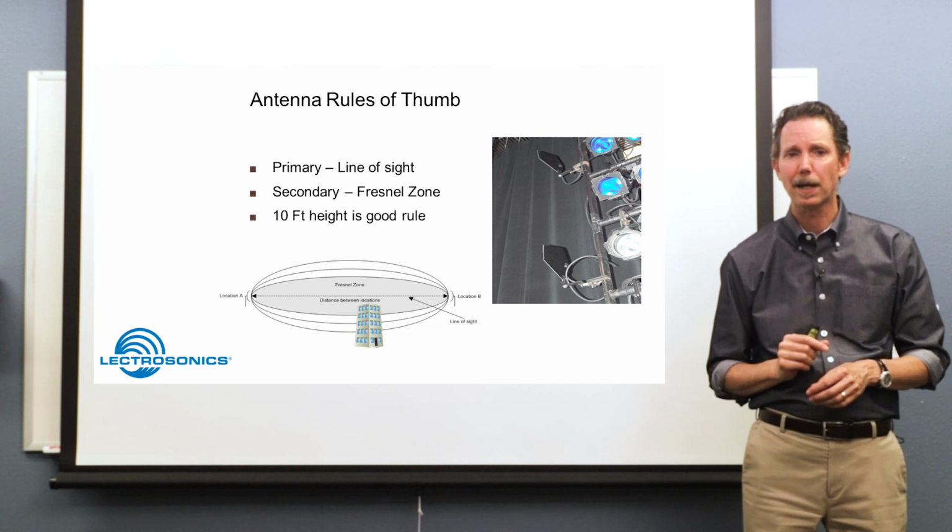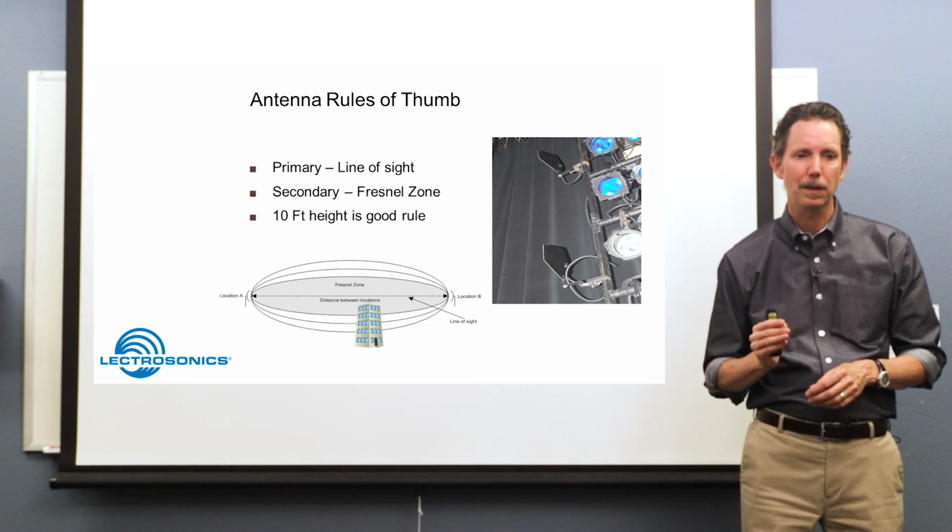So the picture on that slide shows you vertical mounting of 2 directional antennas for a church. So there you see that they're pointed down towards the area of activity where the transmitters would be used, and they're separated by a certain amount of distance so that you have diversity.